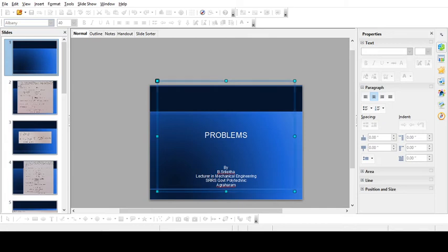Now it carries a tensile load of 400 kilonewtons in the direction of its length. So here we have denoted it with x. So the length is along the x-axis, that is 250. So along this axis only its load is there, that is 400 kilonewtons. Next, a compressive load of 4 meganewtons on its 100 by 250 face.